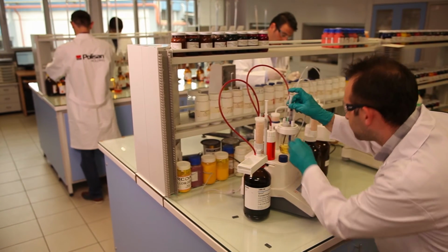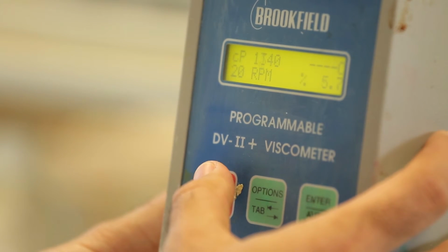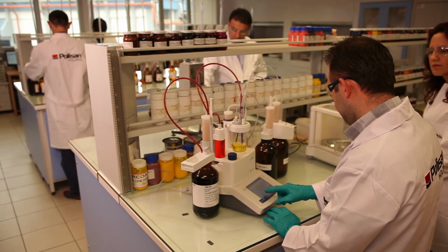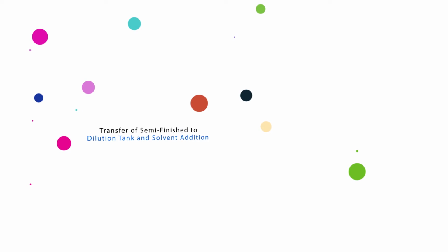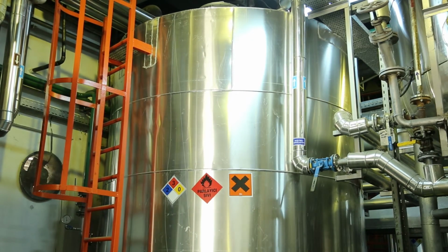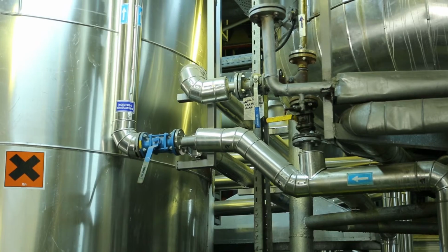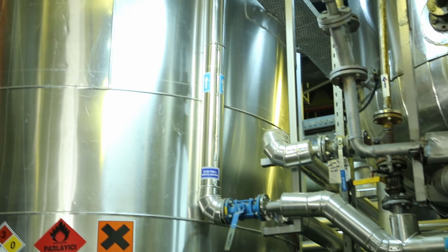Interim quality control. Until the achievement of desired product specifications, parameters such as acid index, viscosities, etc. are checked. Transfer of semi-finished to dilution tank and solvent addition. Semi-finished product cooled down to a certain temperature is transferred into the dilution tank. By sampling from the semi-finished product in the dilution tank to see the solid substance proportion, solvent is added as per the result.